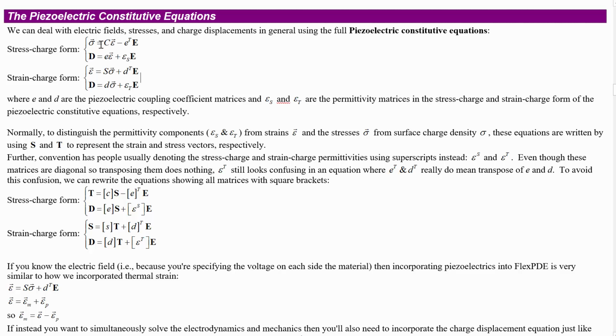So we've already seen this a little bit. This is the stiffness matrix, C, and S, the compliance matrix here. If we have sigma equals C epsilon, then when we invert C, we have to have the thing that's in front of the sigma there be the same thing. So that's giving us epsilon is S sigma. We've seen that before.